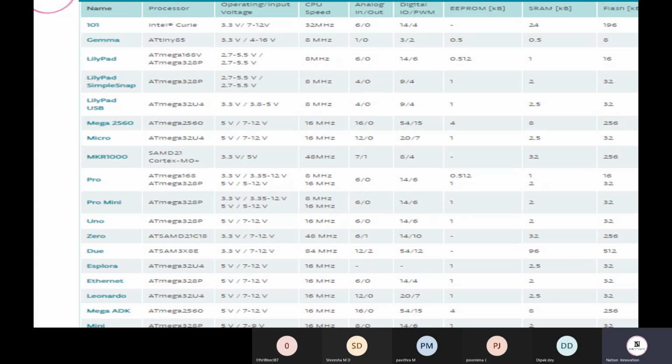And that is what we are having over here. If we are not able to generate the analog direct pulse, we use this PWM functionality. We change the length or the width of the pulse, for how long we want it. It can be 1 millisecond long, 2 millisecond long, or 50 millisecond long. This is what the PWM functionality helps us with. It basically helps us mimic an analog functionality.